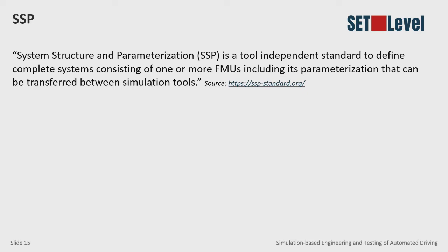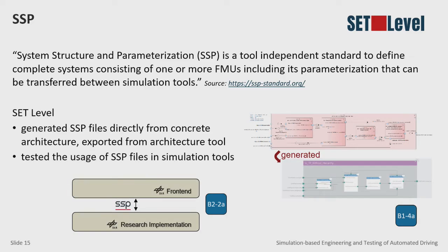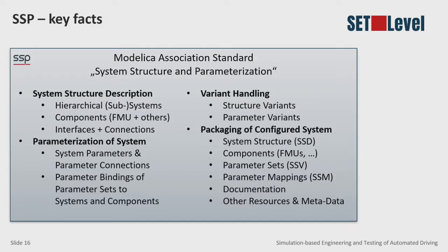The last one is SSP, and that's a standard for configuration of FMUs. And here we looked into how to generate SSP files from a UML definition of an architecture, and here we used Enterprise Architect models for that, and we tested the usage of SSP in a couple of simulation tools. So you will get more information at the booth I point out here.